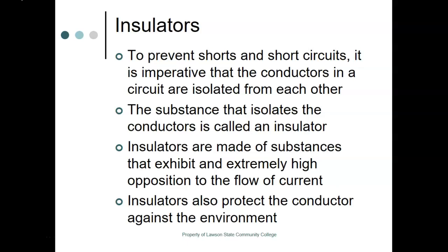You do not want to overheat one of those lines, and I don't know that an insulator would last very long against it. So the major transmission lines that you see out on those big metal frames are aluminum, and they're not insulated.